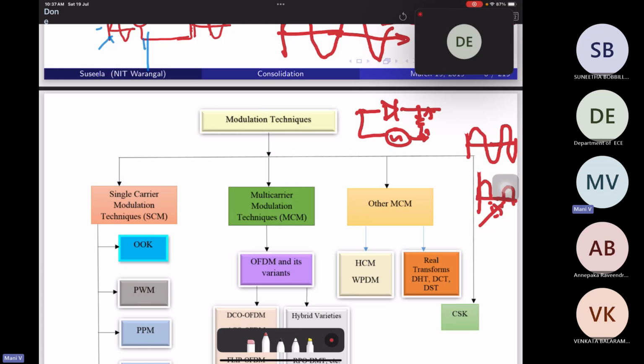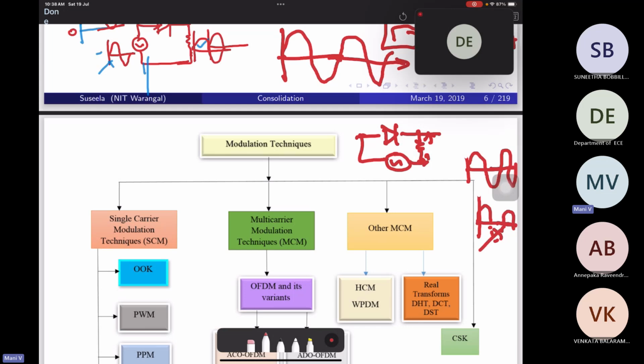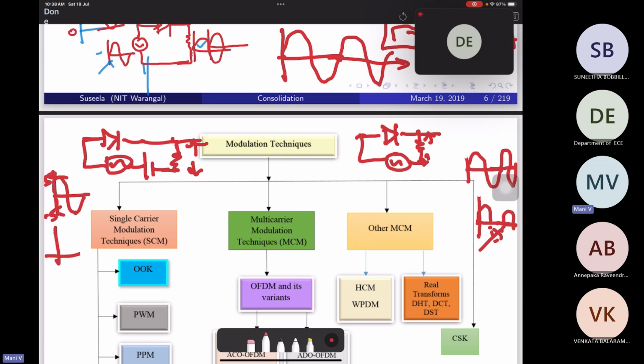So one idea that comes from this device is to shift your information. If you add some DC source to this information, there is a possibility, because the diode conducts for only positive values, that it is all the time positive. So if you add AC plus DC to your information, there is a possibility that it can transmit the signal all the time, right? So now my device is added with an AC source and a DC source. My AC is from 5 volts to minus 5 volts, and my DC voltage is another 5 volts.